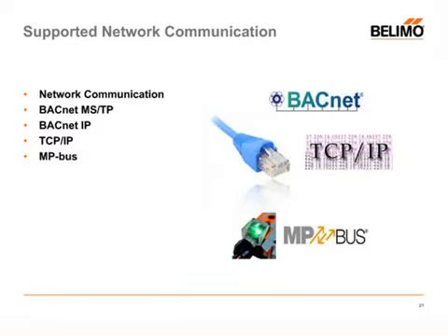So we talked a little bit about BACnet. We talked about our network communication. The energy valve is capable of BACnet MS/TP, BACnet IP, TCP/IP, and Belimo's proprietary MP-Bus.